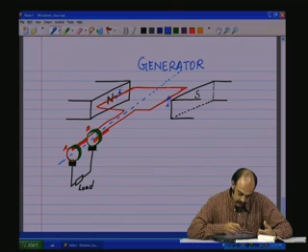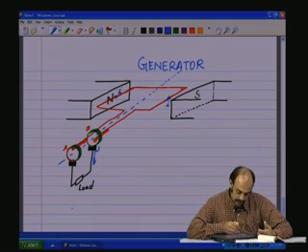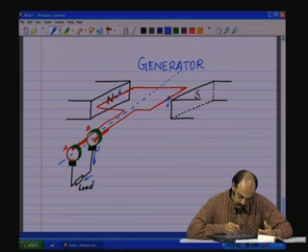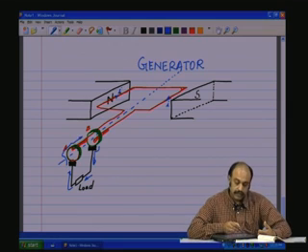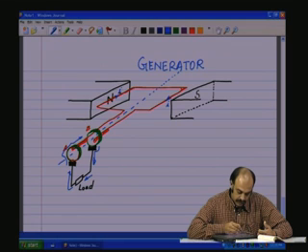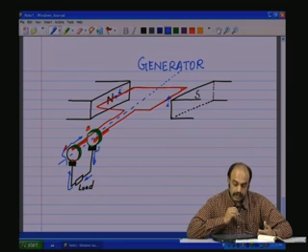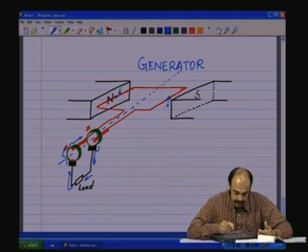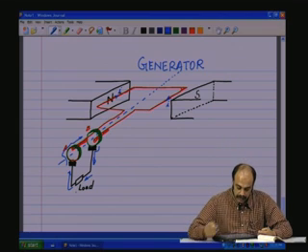This current which flows through here comes into contact through this brush, flows through this external load, and then flows in this direction, and then again flows into the other coil A through this ring and the soldered coil end, which completes the circuit, and thereby you get an output here,